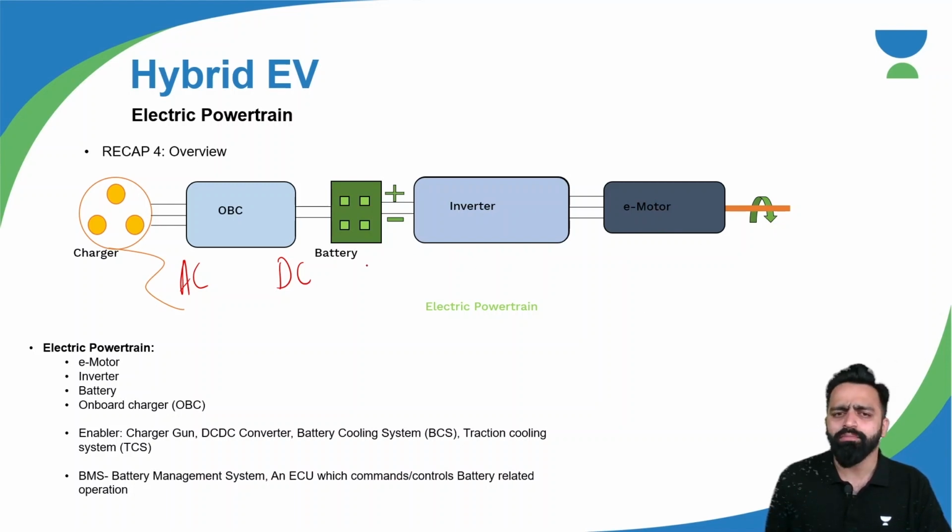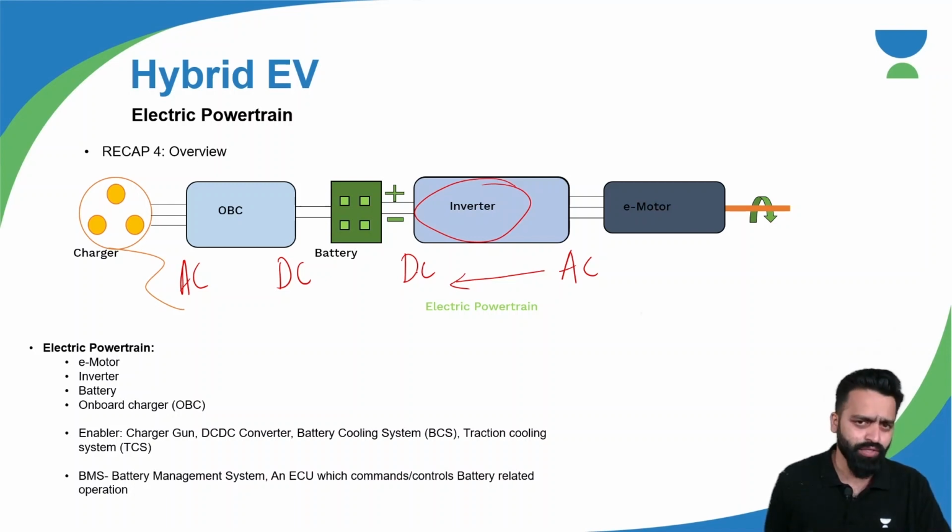Meanwhile, in between the battery and the motor, we have some power electronic interface, which can be called a converter or inverter. In generalized terms, it is called an inverter because it is converting DC into AC. But we are considering the regenerative braking feature also. The power has to flow backward also. That means it has to convert AC into DC also. For that case, it has to be bidirectional. So, moreover, it is called a converter.